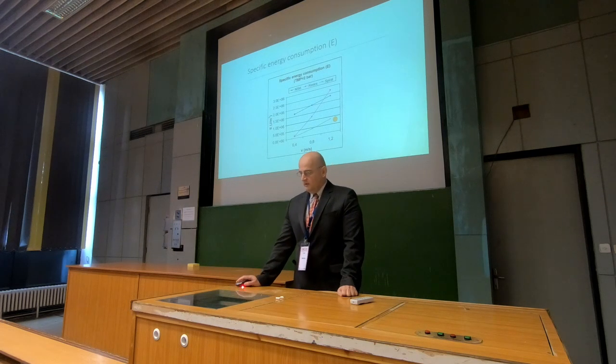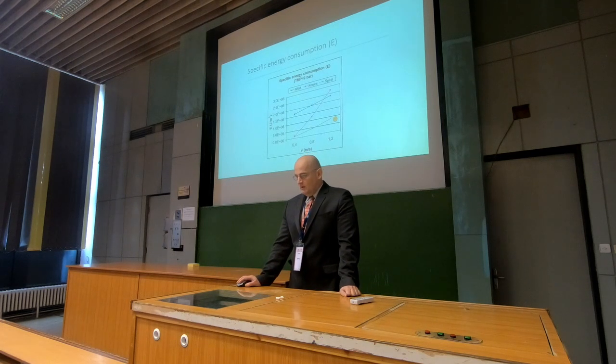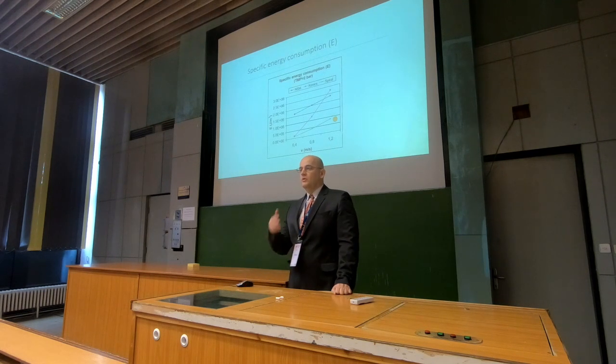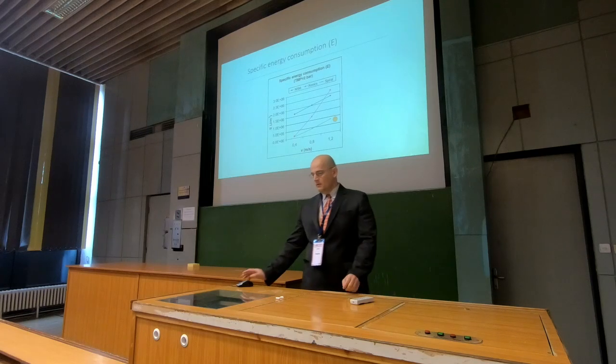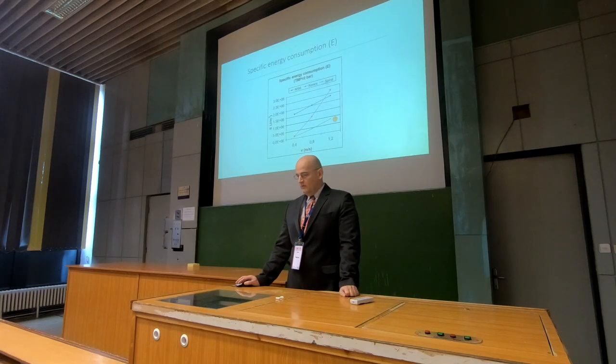And here you can see the specific energy consumption. When we started, we knew that the Kenix static mixer can be used only at lower flow rates. At higher flow rates, it has a very big specific energy consumption, but the new spiral static mixer, even at higher flow rates, has lower specific energy consumption.